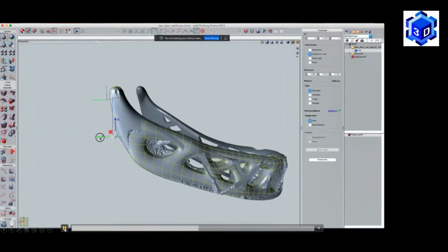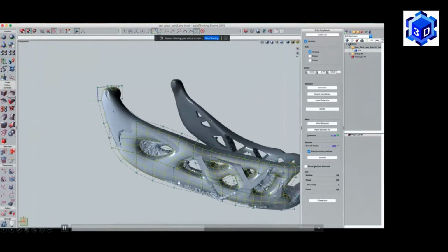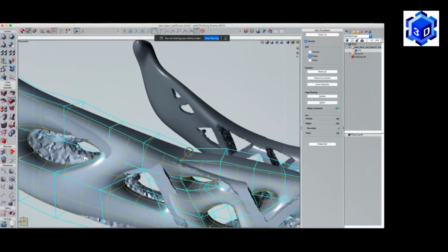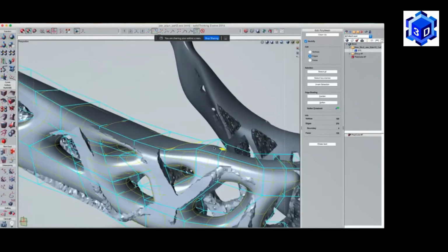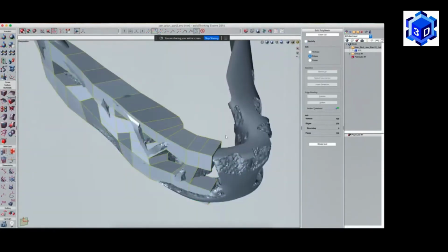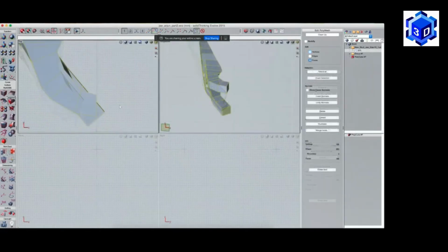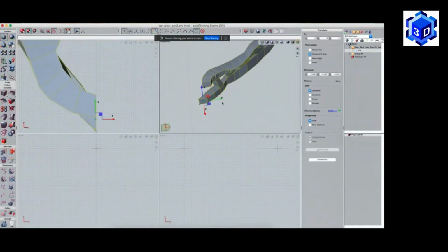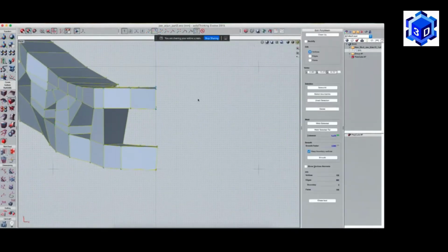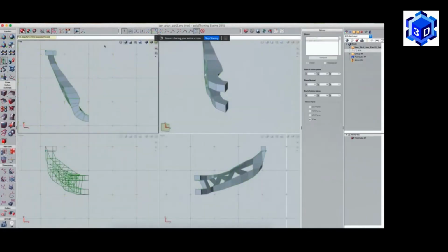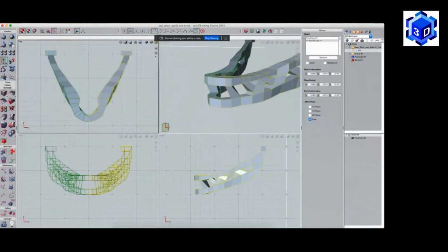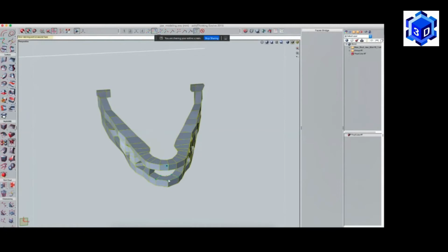Perfect. So once this modeling is done, we call it polynurbs, and polynurbs is a watertight model. That means you can export it, you can make a CAD out of it, you can do all those CAD operations, you can open it in another CAD software, you can even perform another level of, say, FEA analysis on it. And these are sub-D, so each block is activated to edit. So you can edit points, you can edit lines, you can edit sides, you can even edit a group of blocks as well, and so on. So you can make it hollow, you can make it solid. So there are n number of possibilities.